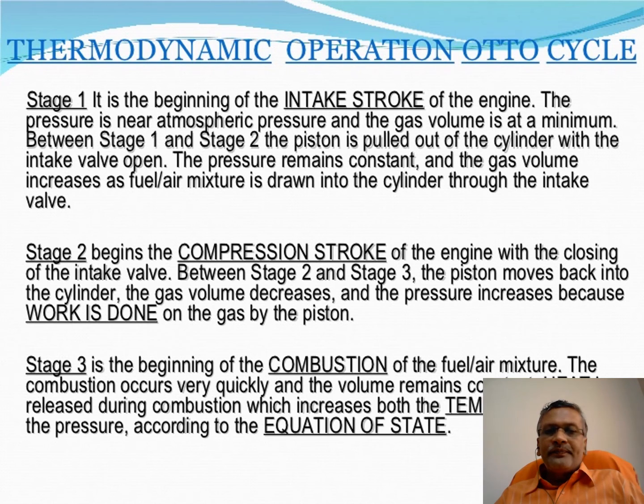Stage 2 begins with the compression stroke of the engine, with the closing of the intake valve. Between stage 2 and stage 3, the piston moves back into the cylinder, the gas volume decreases and the pressure increases because work is done on the gas by the piston.